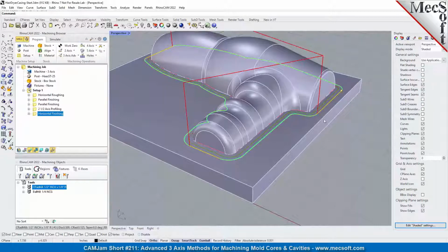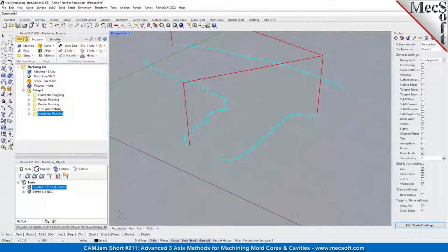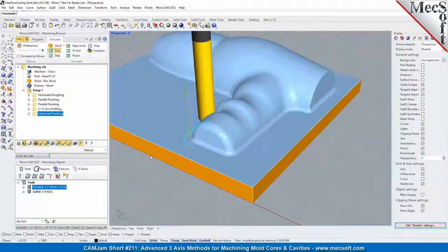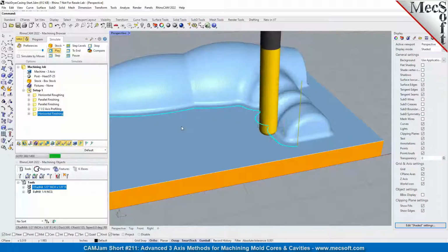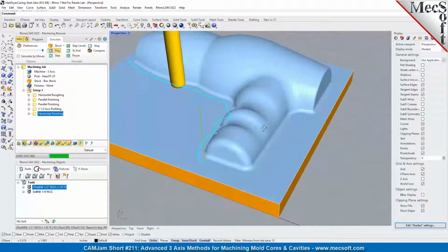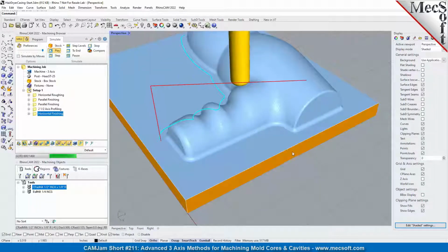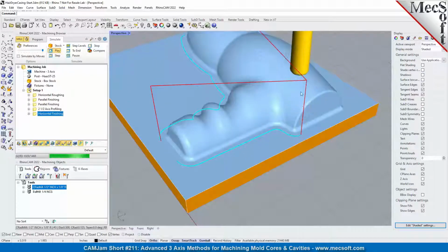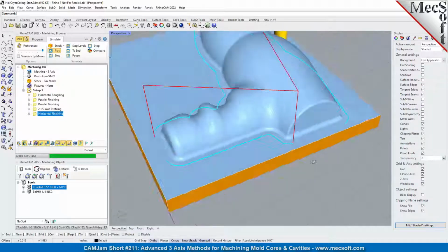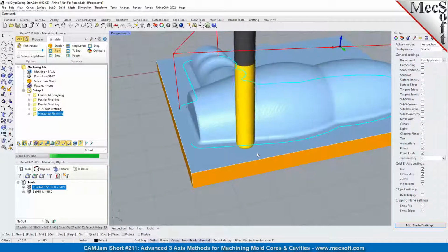Okay, here we go. So what you see is we have a cut level in the bitangent areas. And you see that we have 1 cut level going around cleaning up this fillet. And then it's going to do this area here. And in this operation, that tool is bitangent to each of the contoured areas and the bottom. So we get a nice clear 1/8 inch fillet radius.